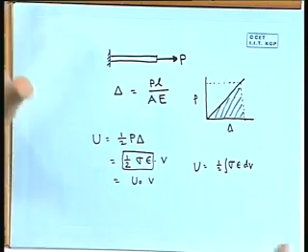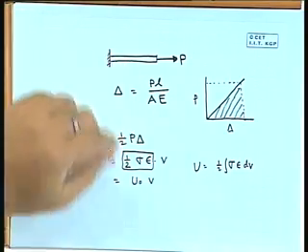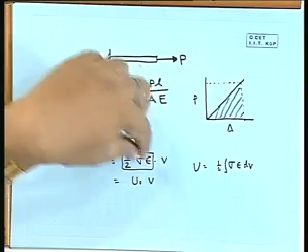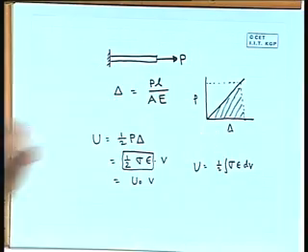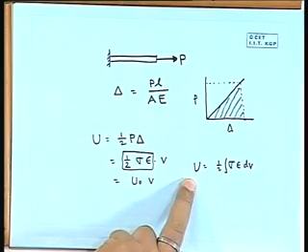So, if we take a case where stress and strain are not uniform, it is varying, this concept is valid for a small point, for a small element. So, that concept applied, V became dV. So, if we combine all the elements, we are supposed to get the expression of strain energy as U equal to half integration sigma epsilon dV.